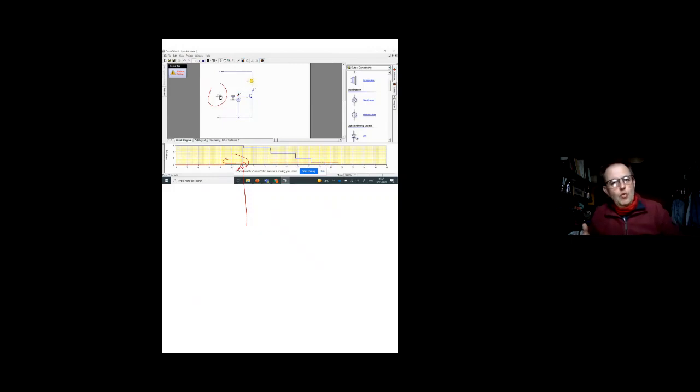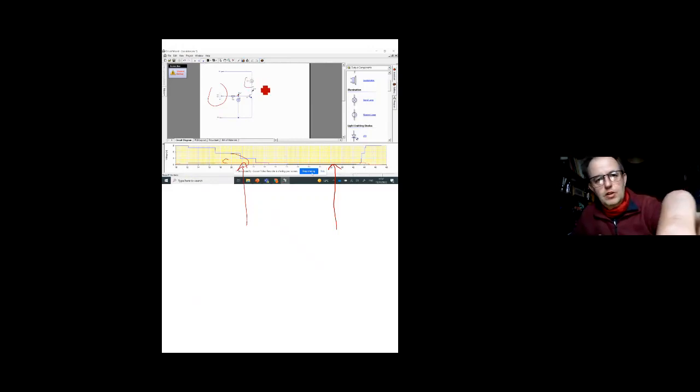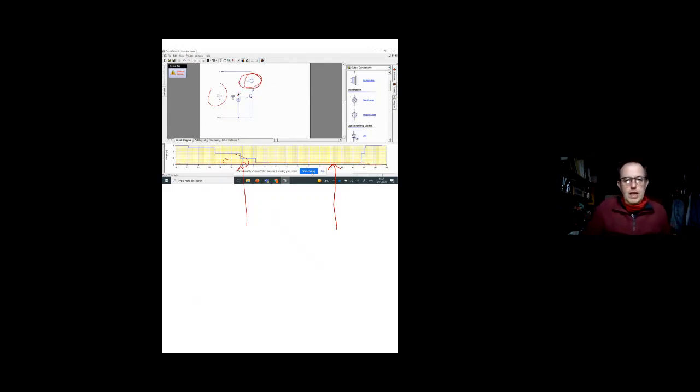We're in the linear region, and now we're in saturation. Once we're in saturation, the output voltage of the transistor is very, very close to 0. So it's more or less giving you 0 power output on the transistor, which is good. All that voltage when you're in saturation is now given across whatever is on the load. In this case, it was a bulb.